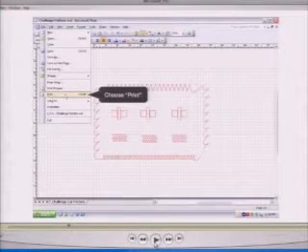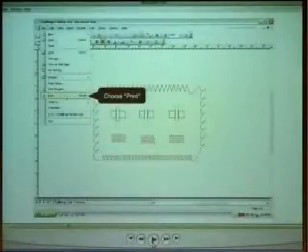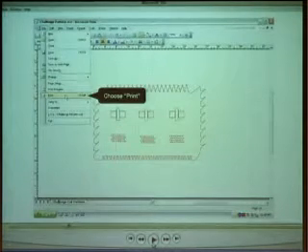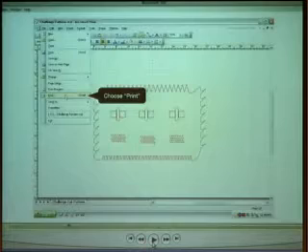So we just chose a kind of complex graphic here. This isn't anything useful, but we wanted to do a pattern that would demonstrate the capabilities of a laser with respect to a rotary cutter or a knife cutter or a die cutter. Things like this shark tooth pattern are very sharp, and if you tried to cut it with a rotary cutter, you'd just tear the edges off. These square rectangle patterns have about a 15 thousandths wall between them. So if you tried to cut those with a die, you'd probably pull it apart. And that's the reason for this oddball shape. So I'll just run through it from here.